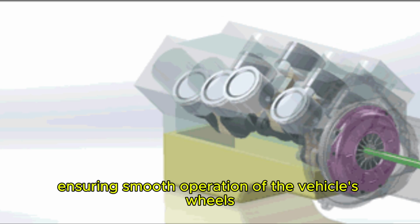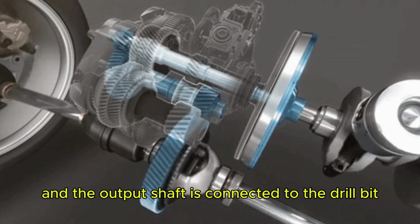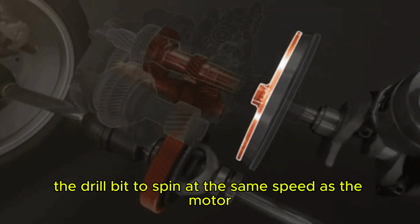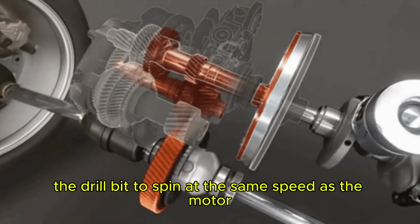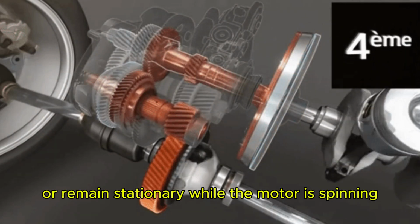In electric drills, the clutch's input shaft is driven by a motor and the output shaft is connected to the drill bit. The clutch allows the drill bit to spin at the same speed as the motor, spin at a lower speed, or remain stationary while the motor is spinning.